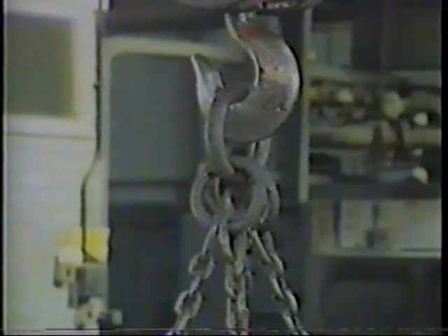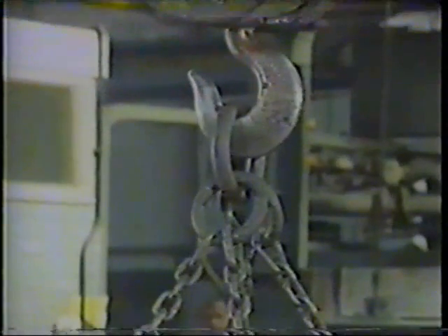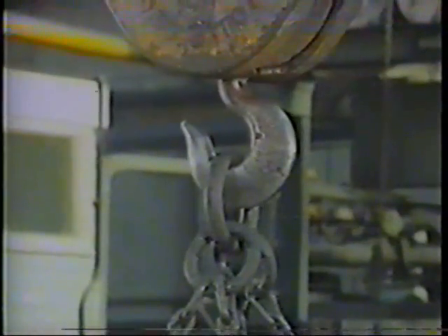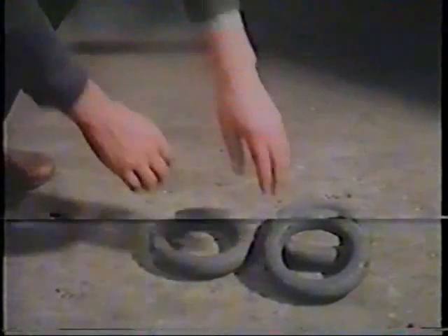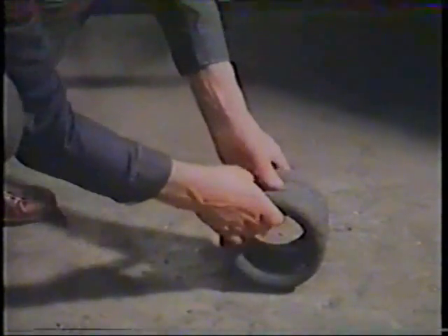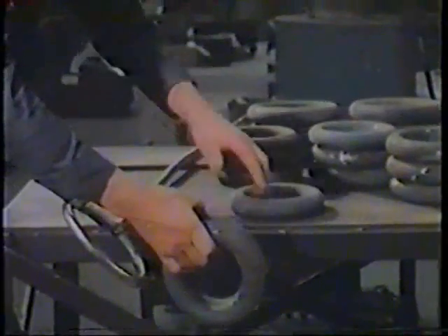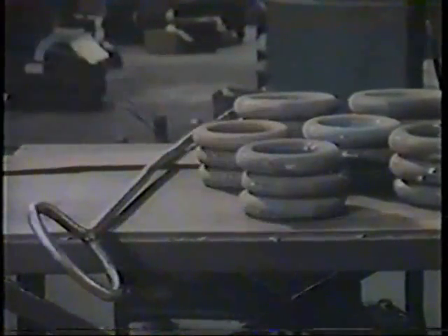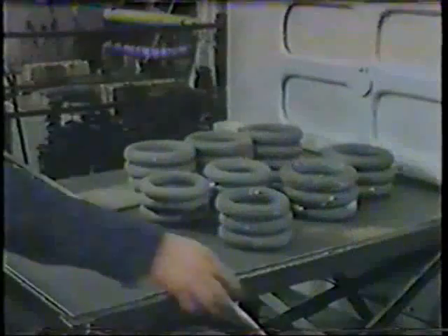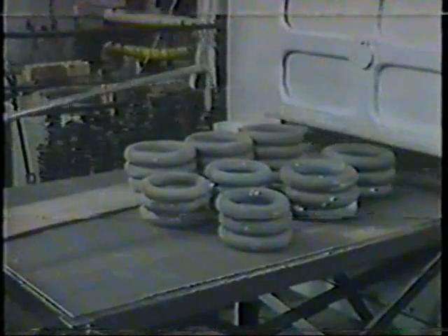Here's a situation where toughness is an important property. The large steel links used in lifting gear are often made by forging. This can leave the material in a stressed condition, with properties unsuitable for the job it has to do. These stresses can be relieved by another heat treatment process known as normalizing.